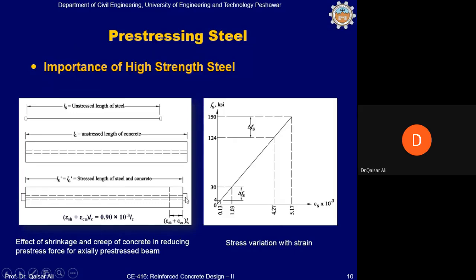Okay, so through this anchoring mechanism on both ends, now the compressive force will be applied on the concrete beam, unlike the previous case where the compressive force was applied through bond between steel and concrete. So the previous case was the case of pre-tensioning, and the second case is the case of post-tensioning. In both these mechanisms, we can produce a pre-compression force in the beam. Okay, this we will discuss.